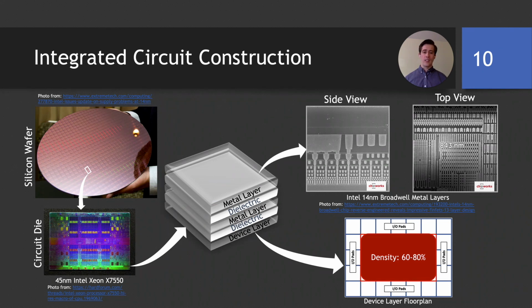And the second is that the CAD tools that automate the place and route process employ heuristics to identify viable routing solutions for a given layout. Reducing density makes it easier to find these routing solutions.